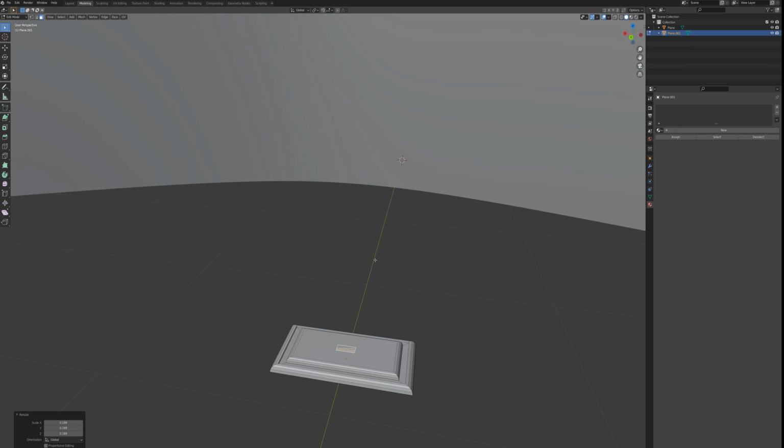I'm going to press R Z 90 to turn it, G X over here, E to extrude, and let's see, if I press Control B, I can round this edge off. No, Escape. I'm going to press L, hovering over this piece to grab the whole thing, and let's see, Control B. Yeah, okay, so this is pretty much what I want to do here.